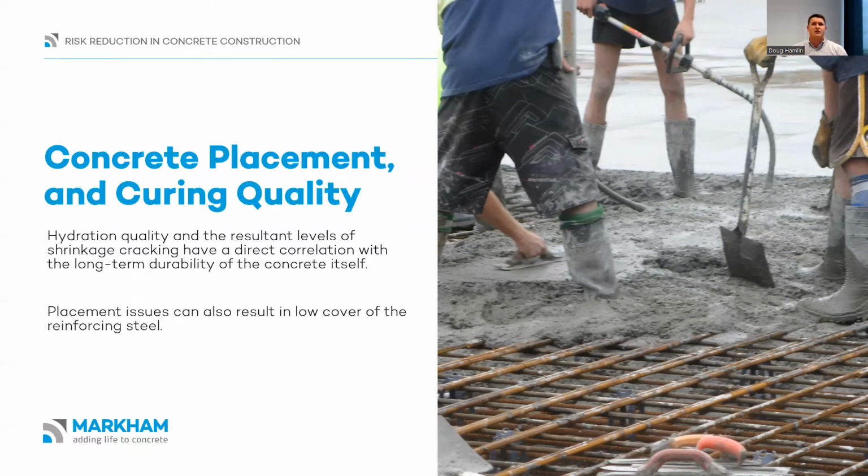This is in all the engineering handbooks on concrete, that curing a concrete is very, very important to the long-term quality of that concrete. And it basically is because if you don't get that concrete hydrated properly, you can lose out on strength, obviously, but you can result in shrinkage cracking or excessive shrinkage cracking, that type of thing.